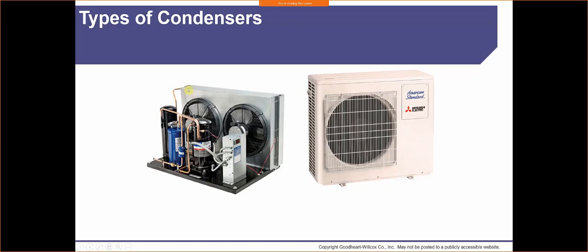Now what ends up happening is, as the temperature outside decreases, I don't need as much refrigerant in my system to maintain the temperature, because the natural ambient temperature outside is keeping things nice and cold. So if I left the system alone with the refrigerant charge in there, I would have to come back every couple of weeks, or weather depending, to adjust the charge in my system.